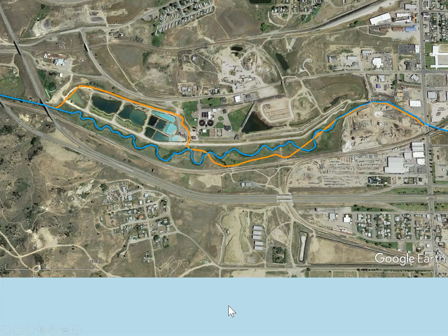So let me describe what else you're seeing here. They've rebuilt this floodplain. Remember, they've removed over 1 million cubic yards of tailings. Now they've built a water treatment facility, groundwater treatment facility. It's just simple lime addition. So lime's added in these first basins. They're light blue because they're precipitating out metal hydroxides, and it's scattering light and it looks light blue. The discharge from this system is down here back into Silver Bow Creek, and that discharge meets water quality standards